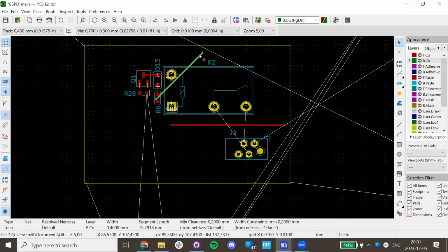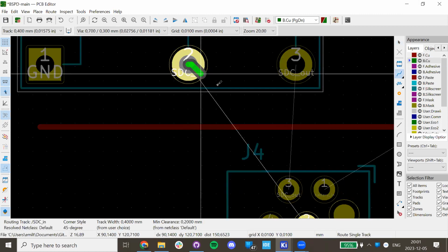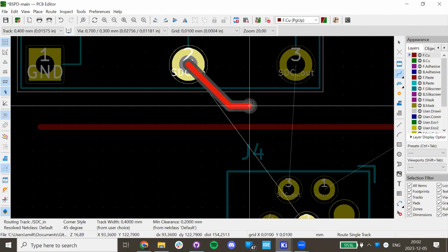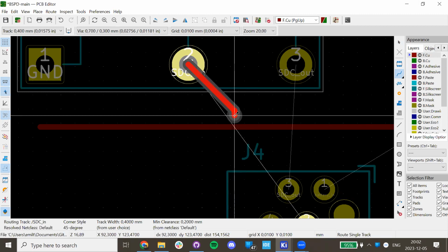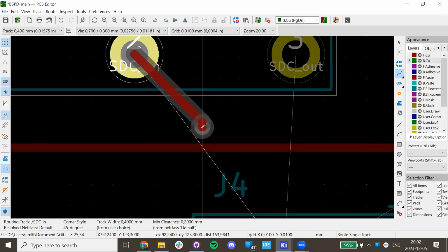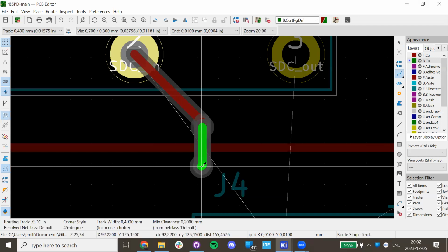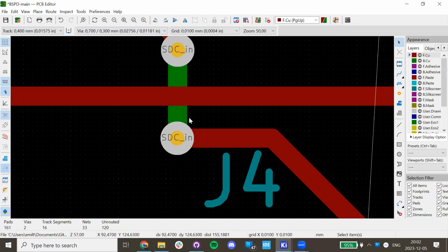And if you find that your PCB is so constrained because it has to be small that you can't reduce the size of these big traces, you can add more layers, which I will show you. But so if I want to route here, I go into the front copper layer, and what you can do then is you press V. V automatically gives you a via. So I go very close and I try to be perpendicular to the trace below here. And now I'm going on the backside and I press V again, and I try to like this. So you see how I now went under the trace.